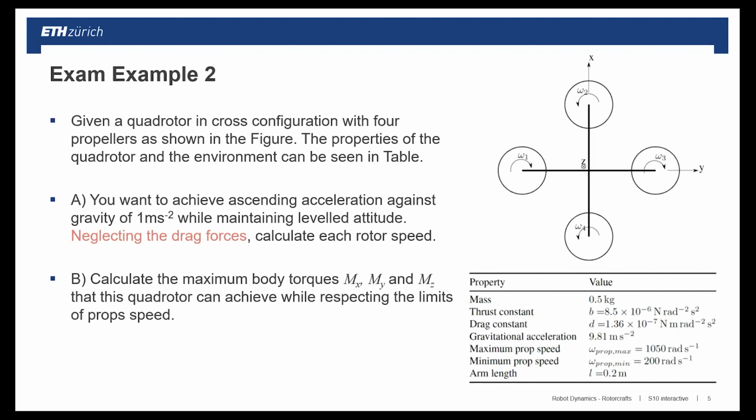At very low speed, there is an issue that you cannot measure the speed correctly because they have no specific sensors. Typically, they measure the rotational speed by induced currents, and so they are not really running smoothly at very low speed. And of course, the maximum speed might be limited by the converter, by the propellers themselves, and so on.